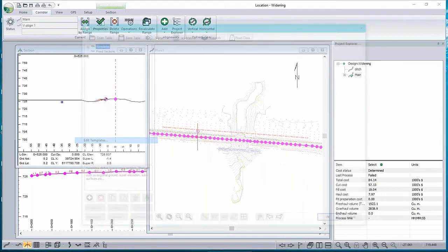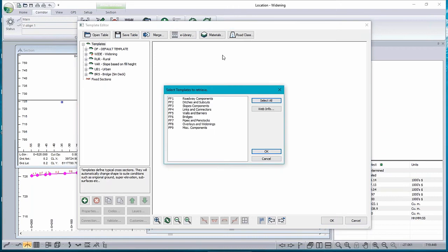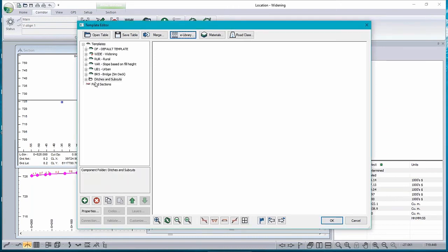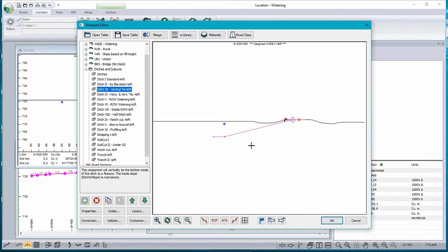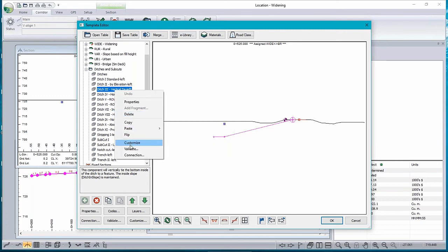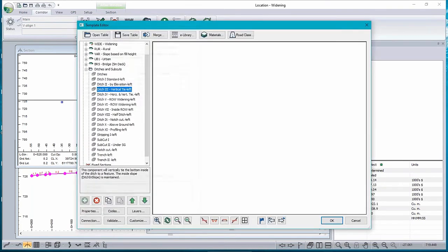That's a template function, and I just need to replace the ditch template. So here's a ditch with a vertical tie. So what that means is it's going to connect the elevation of the ditch to the reference feature. You can even do it in here if you want. Depth, use reference feature, number 2, and there it is. Okay, and now the elevation is changed.